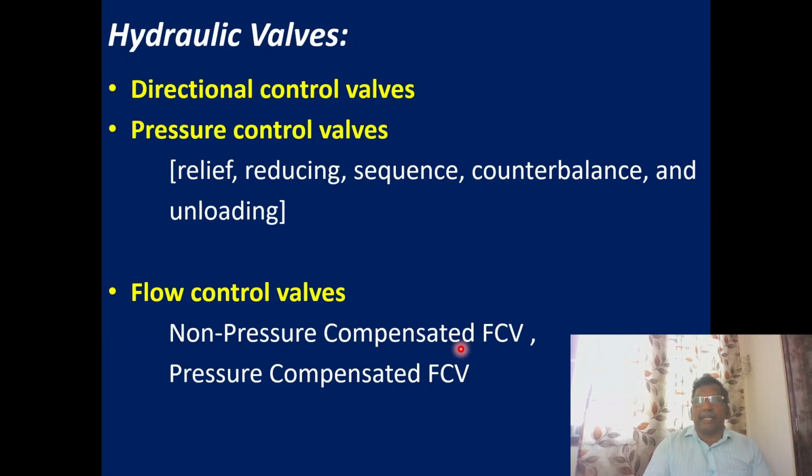The next, valves we are having, hydraulic valves. We have different types of valves: direction control valve, pressure control valve, and flow control valves. So direction control valve, we are having types of direction valves, we can see that one. And pressure control valves, in hydraulic systems, we are using relief valve, pressure reducing valve, sequence valve, counterbalance valve, and unloading valves. Flow control valves also we are having, non-pressure compensated flow control valves also.